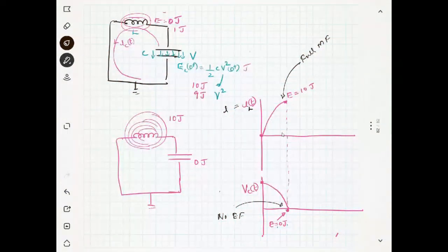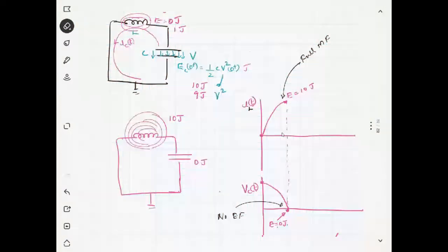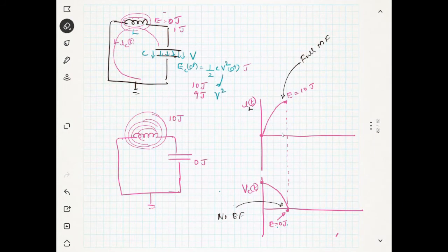Doctor, you said here the capacitor will be short. Capacitor will be short actually. Capacitor will be short means what? Zero volt. It is having no energy. What about the inductor? Inductor is having full of energy and it is having maximum current. It is having maximum current now.